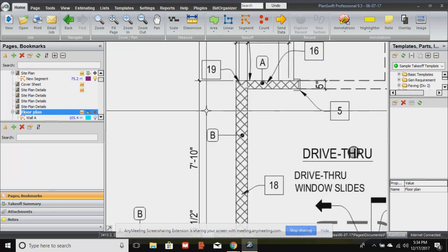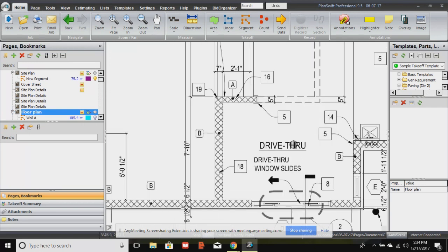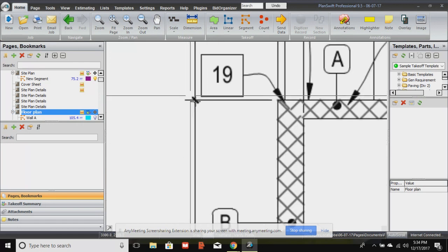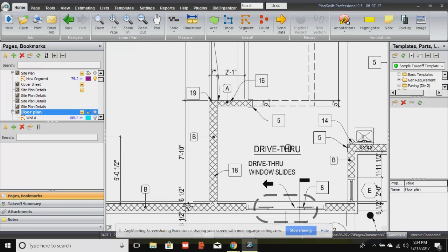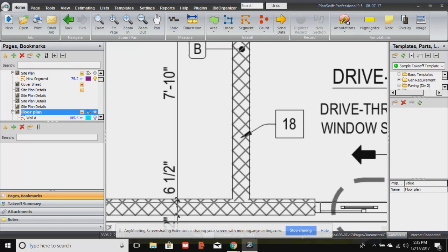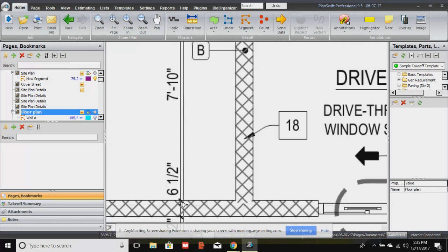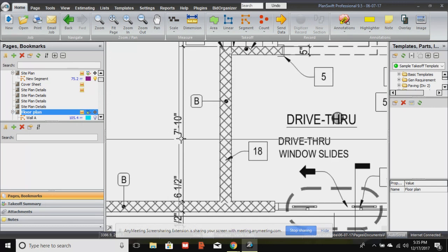And on construction documents, lines, symbols, everything's important. How we read that this 7-foot 10-inch stretch of B wall is from hash mark, which is that diagonal little piece of line that intersects the horizontal and vertical axis, hash mark to hash mark right here at this point. And so the number in between is the actual length.